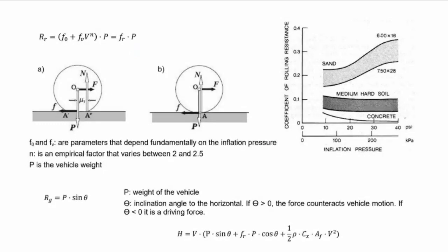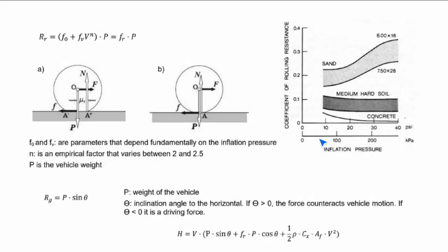Also, rolling resistance is critical. Why? You can see the figure of inflation pressure and coefficient of rolling. You will select from this table. Okay. Rolling resistance will increase with tire flexing work, air resistance, and friction effects on the tire tread.